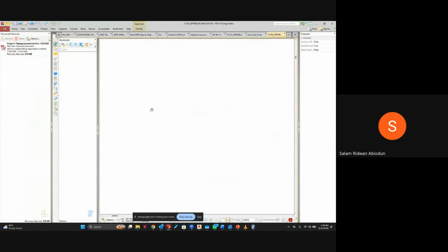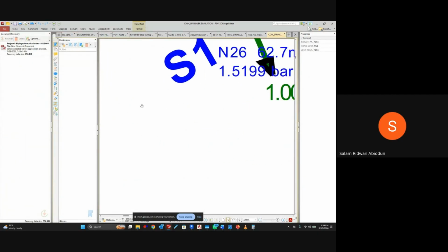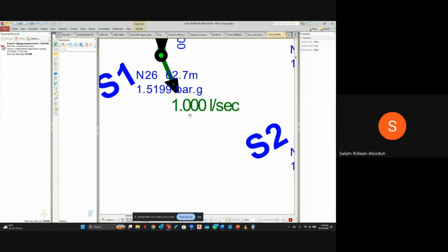Okay, look at what I'm saying. So when I'm having 1 liter per second here, if it is an extended coverage, what you'll be having here will be like 1.82 liters per second. Do you see the difference? Like times 2. And actually, it's going to impact your pump size. It's going to impact your pipe sizing. Now, the funny thing about it is that you are now going to need fewer sprinkler heads because that one will now do more coverage. That's why they call it extended coverage.